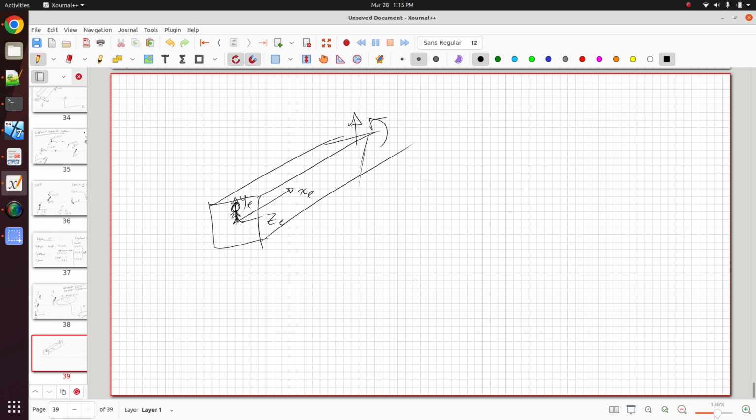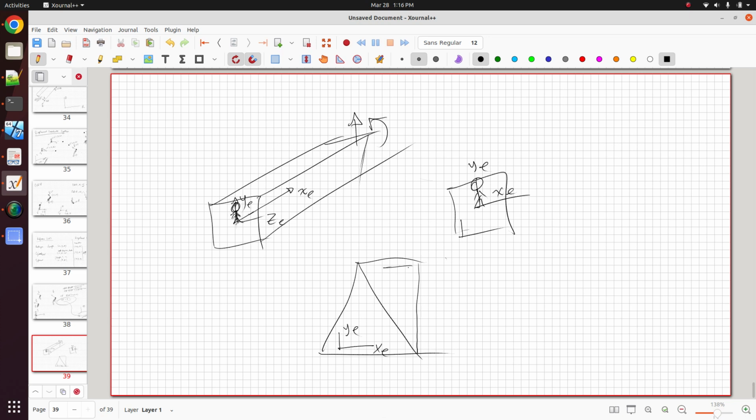Another example, quadrilateral elements also. There is an element coordinate system here. So when you're looking at the stress, there is an observer here, if you will. And why is it important for a 2D element? Let's suppose you have these two triangular elements. Maybe your element coordinate system might look like this for the first element, but then the element coordinate system for the other element might look like this.